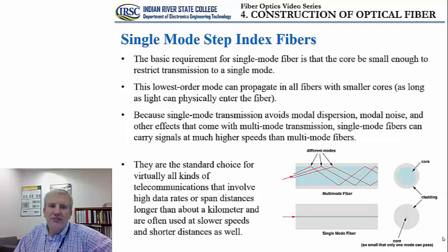So single mode step index fibers are the standard choice for virtually all kinds of telecommunications that involve high data rates or span distances longer than about a kilometer, and are often used at slower speeds and shorter distances as well, if the budget allows for that.